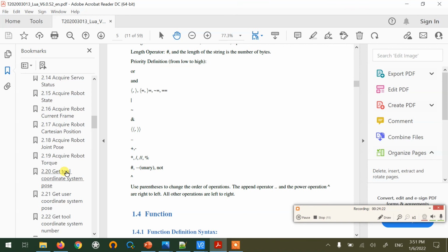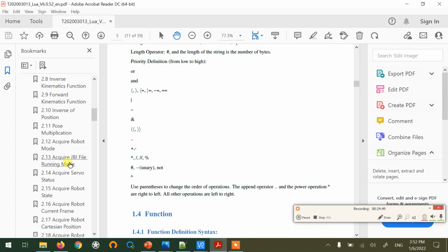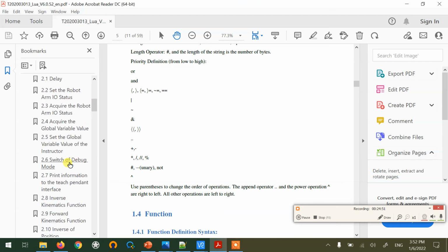With this Lua you can start a UDP server or TCP server on our robot, or you can have some Modbus communication over TCP or over RS485 serial RTU Modbus, and some other abilities that will be provided for you with the internal model.